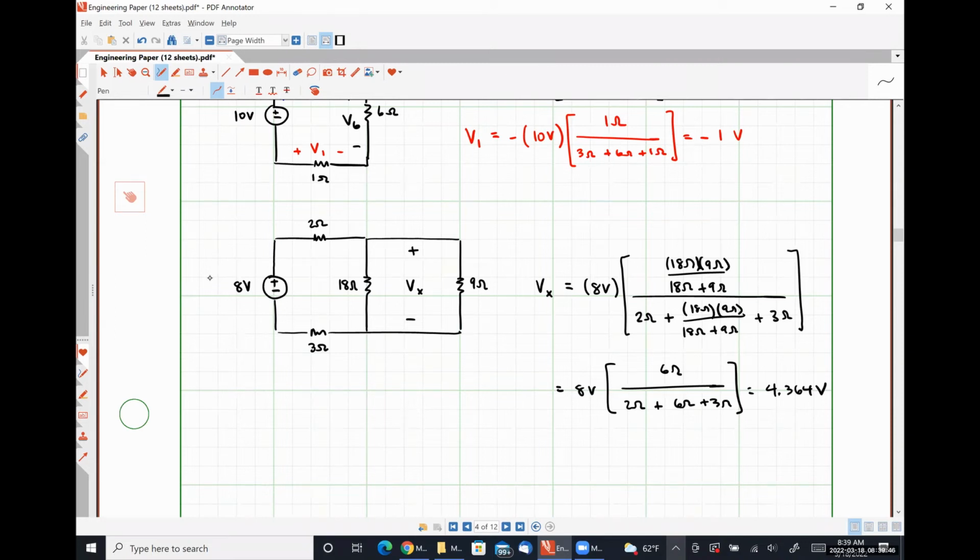So next, we've talked about voltage division here in these last several minutes. We're about to talk about current division, which will take us roughly about the same amount of time as it did for us to go over voltage division. Those are fantastic tools for their specific application of whenever we have resistors in series connected to a single known voltage, or whenever we have resistors connected in parallel to a single known current.